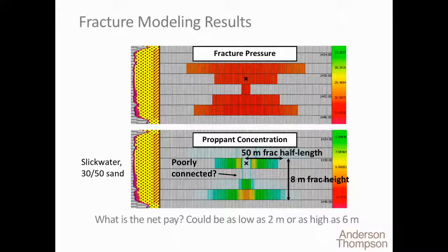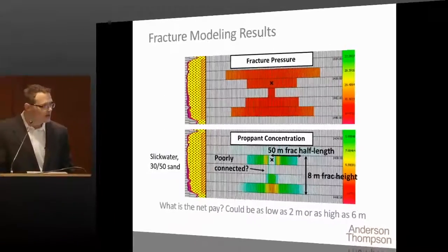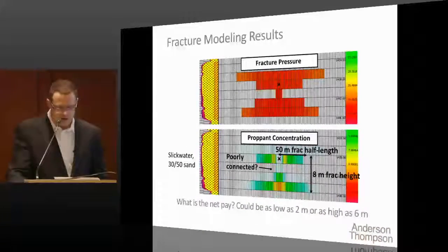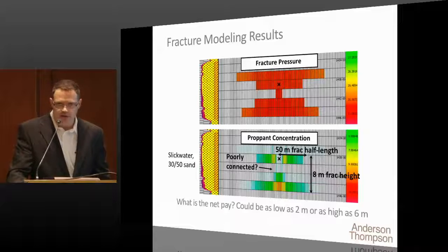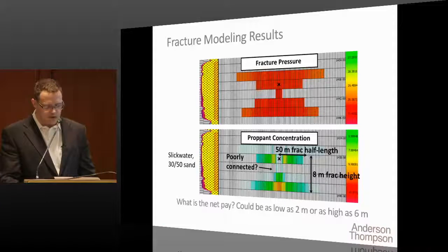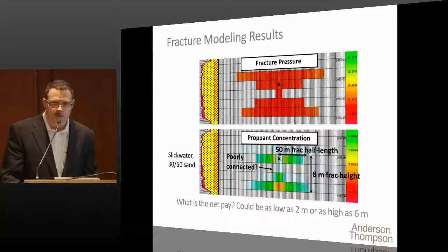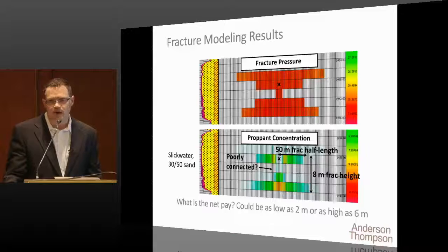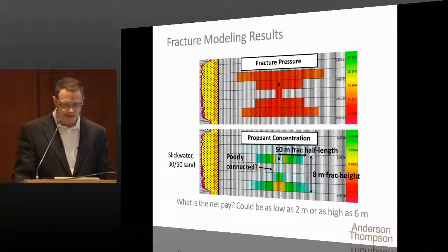After we're more than a couple meters down, there's a bit of a gap, as you can see in the illustration in the bottom image, and then the conductivity, or the sand concentration in this case, gets big again. So we don't really know what to use for H now in our models, but we know 12.5 doesn't make sense. And we can confirm that by using 12.5 meters and coming up with, like I said, nanodarcy permeability in the Cardium.